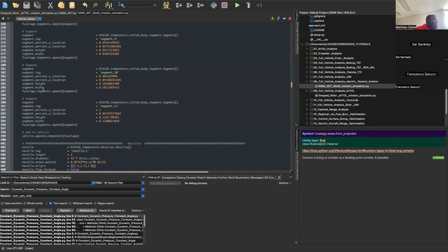For example, I had a discussion earlier this week about how you model a tanker flying. A tanker is flying, so it's using fuel on the engines, but it's also fueling another aircraft. How do you model that at a conceptual design level? Which is a very interesting question, right? Because imagine each fuel tank is going to have a different mdot, or fuel flow rate. That's going to change the weight of the aircraft, and that's going to change stability. So how do you do that in a transient manner? I think we started to figure that out, and I'm working on that right now behind the scenes.